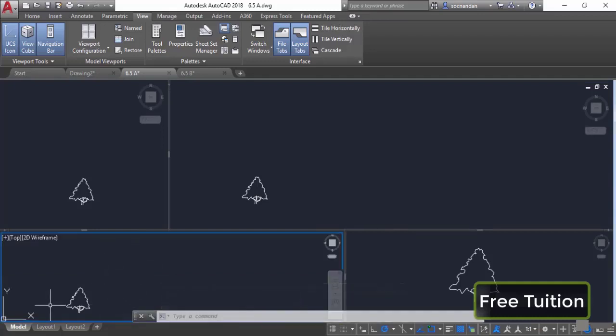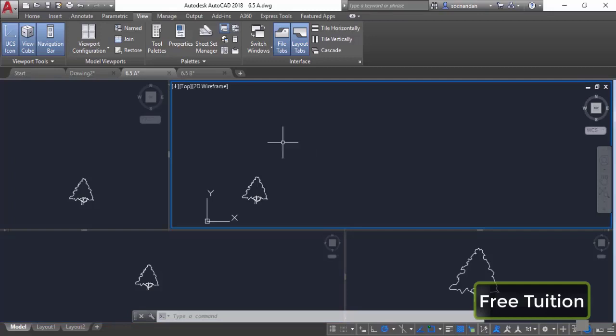And the final viewport will take the configuration of the initial viewport. So wherever you clicked first will become the view of our final joined viewport. In this case, if you want to make any viewport final and if you want to make a full screen viewport, then select it. So here we have it.